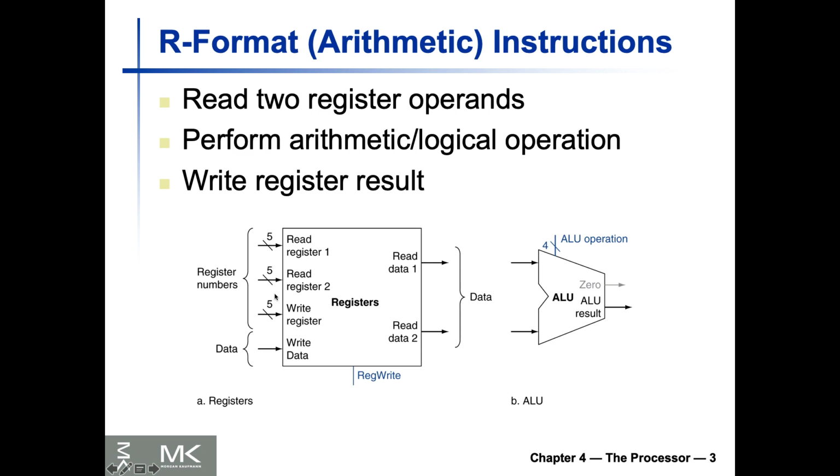I also mentioned that the reason we have 5 here is because in RISC-V we have 32 registers, and the width is either a word or double word, right? So 32 or 64. So this is a simplified version of having 5 lines. Each of them is a signal, either 0 or 1. So I have the option to choose 0 or 1 on the first line, 0 or 1 on the second line, and so on. So you have 2 options for each of the 5 lines, which leads to 32 options, right? 2 to the power of 5.